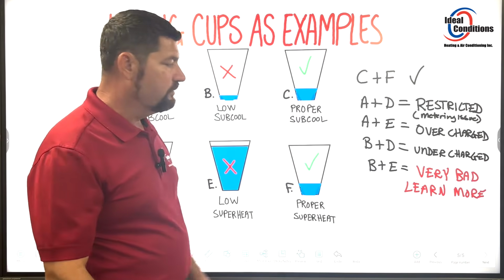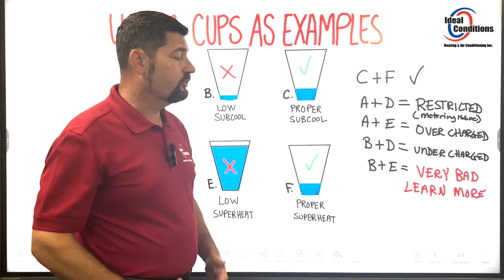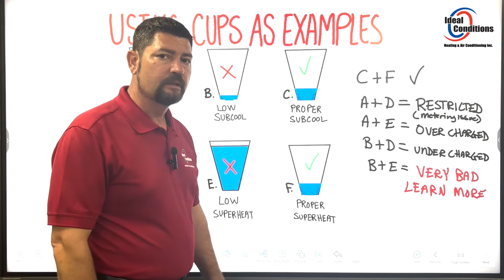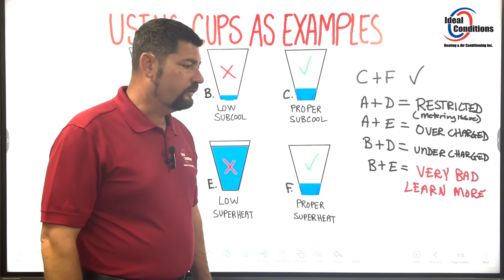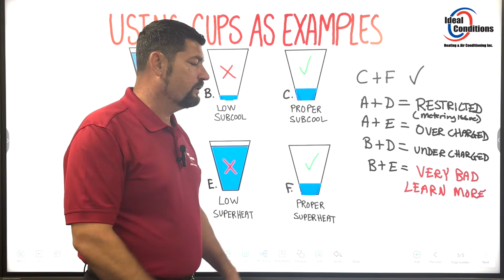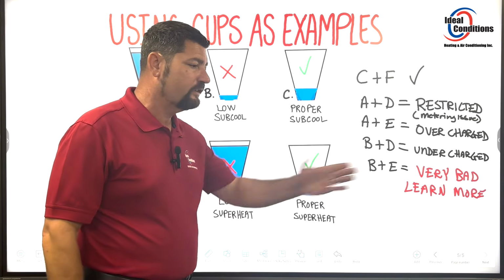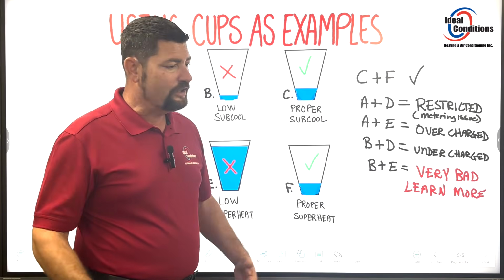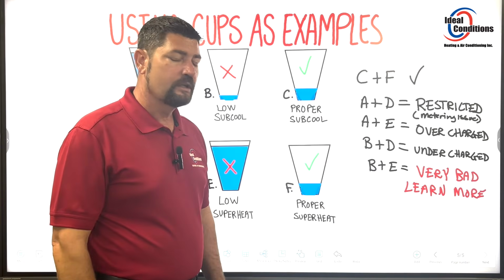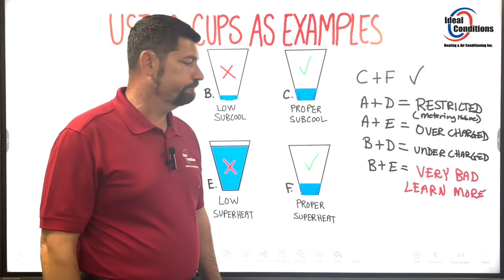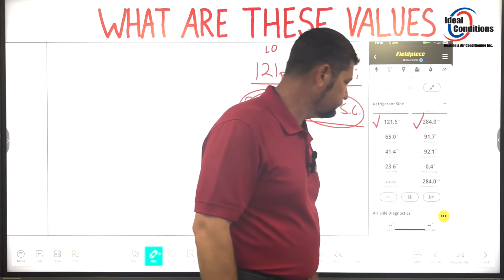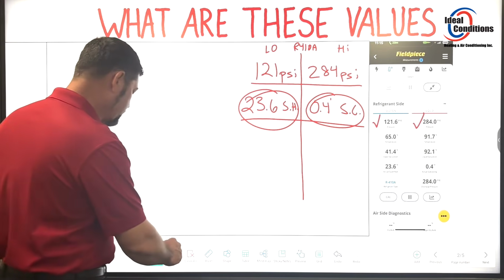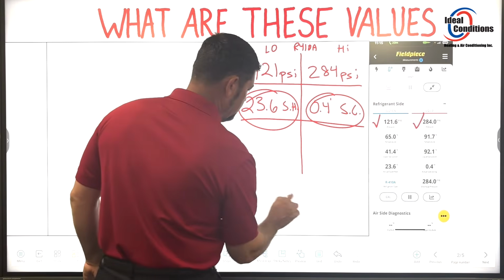Maybe there's not a leak. Maybe you're in the beginning stages of a leak. Should I do a leak check? Absolutely. Unless you can say, hey, that system was just started up a week ago and those are the exact same values they recorded then, they just didn't add a little bit more charge to it. I would definitely do a leak check. All right, let's go ahead and check on another one. Stuff isn't hard.